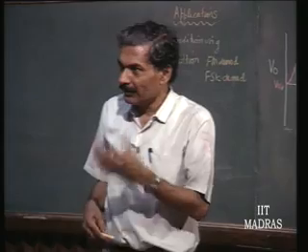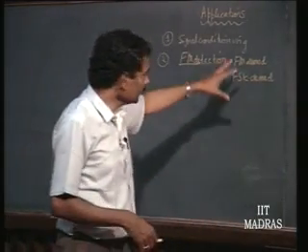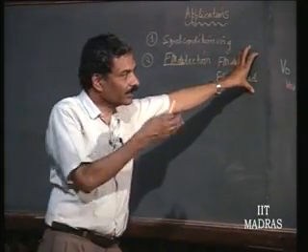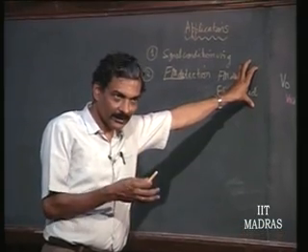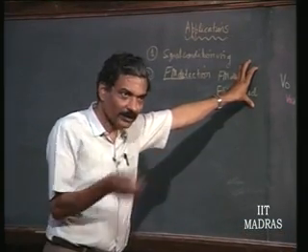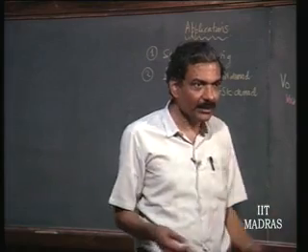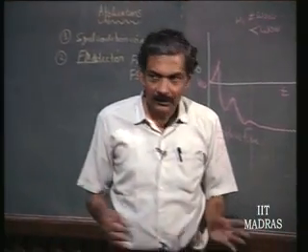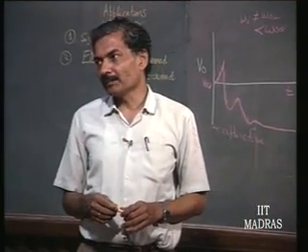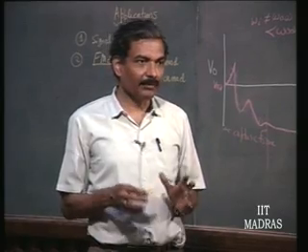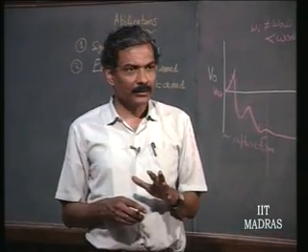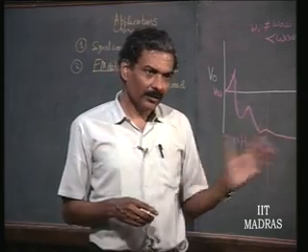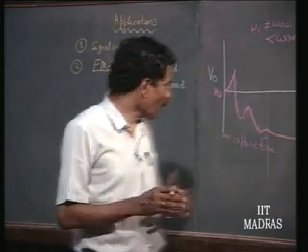So, this property was used earlier, whereas in this case you see that we are using a linear VCO, and therefore, the dynamic range of the FM detector depends upon the dynamic range and the characteristics of the VCO. Okay. So, this is an important aspect of PLL as FM detector, and most of the present day FM detectors, okay, are PLL based. Okay.